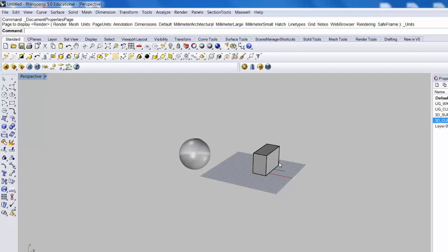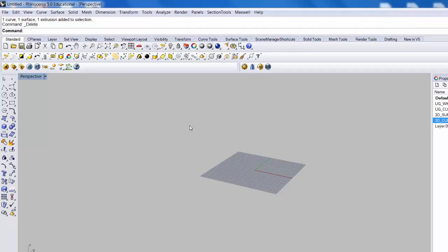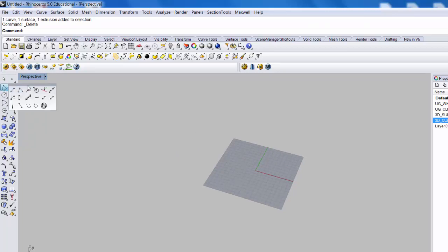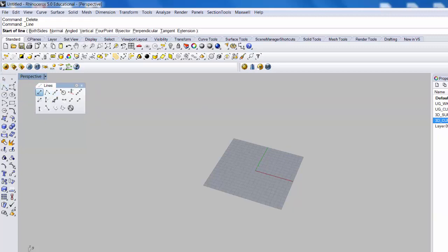So, the sidebar buttons. To make entities, we'll just start with 2D construction, and I'll build up this object really slowly as we do it. Polyline is one button that I'll use. If I just make a line, I want to work on my center line layer. I'll usually start at the origin 0, 0, 0, hit my space bar, hit O to put ortho on. Here's a handy thing: we know we're working in millimeters, but we want the bed to be 6 by 8 inches. I can actually type 6 in, and it knows 6 inches, which is kind of handy.